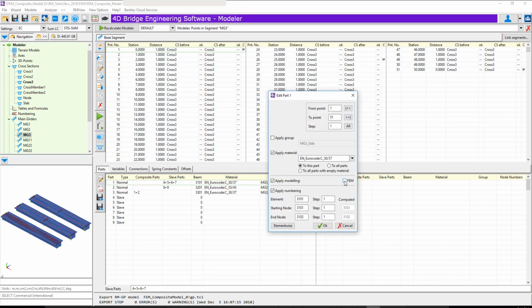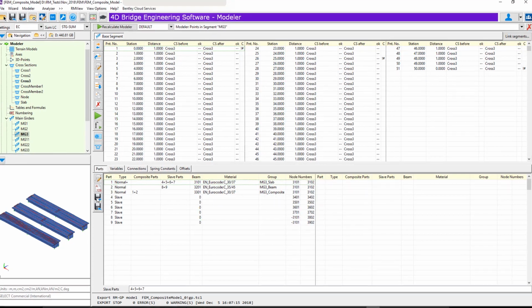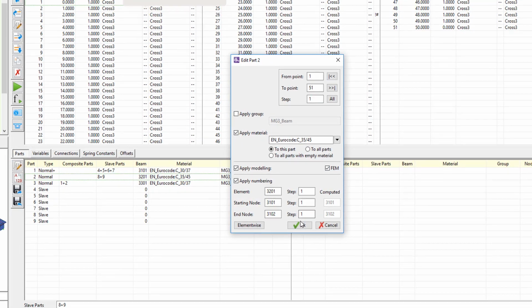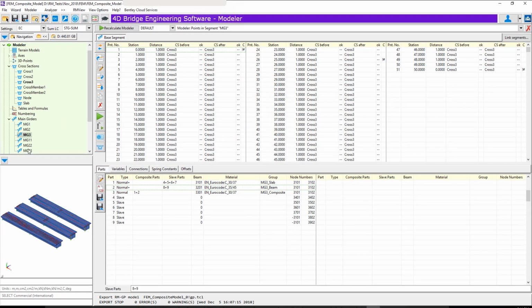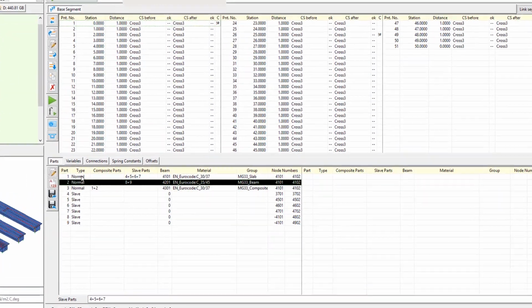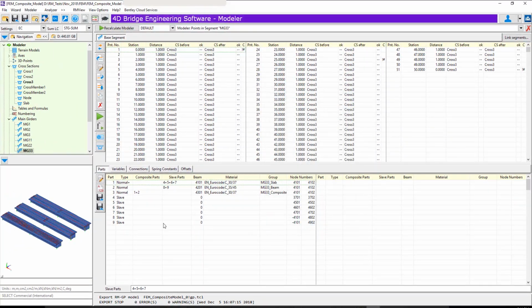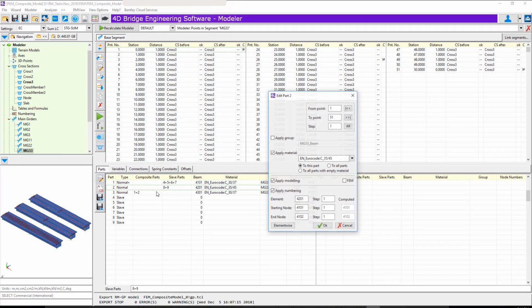In main girders, we assign FEM modeling to all the part elements. For a full composite FEM model, some attention should be given to the connection support elements, for being sure that all the restraints are well defined before and after the support node.